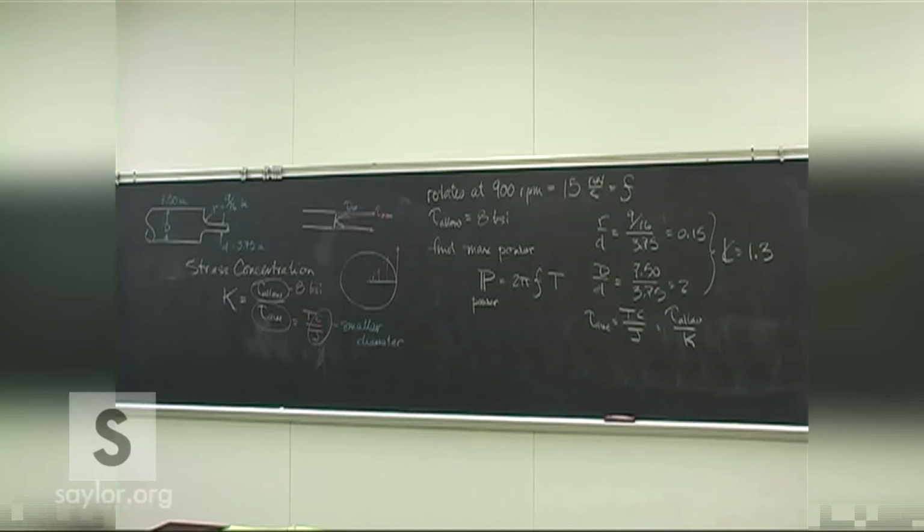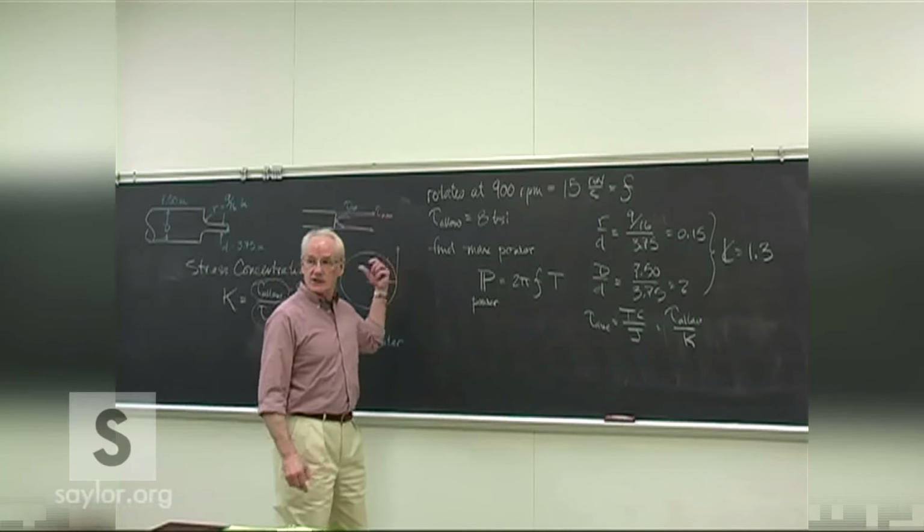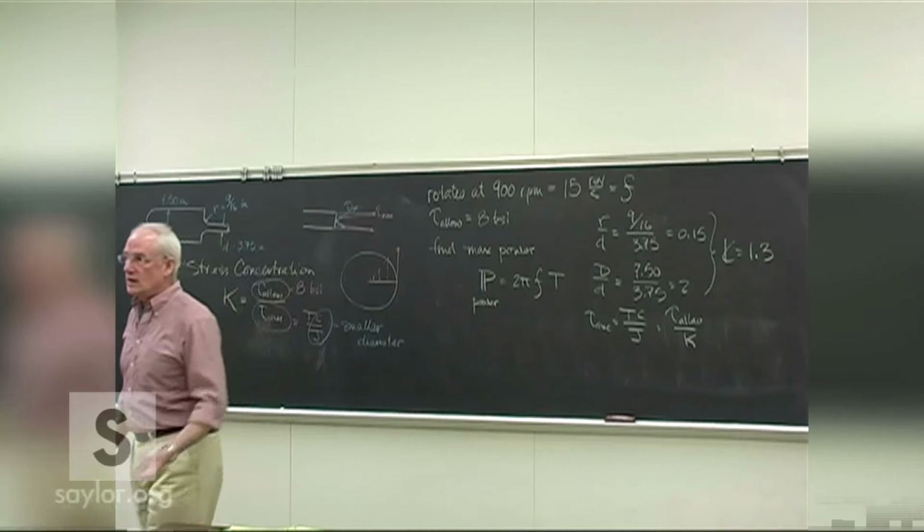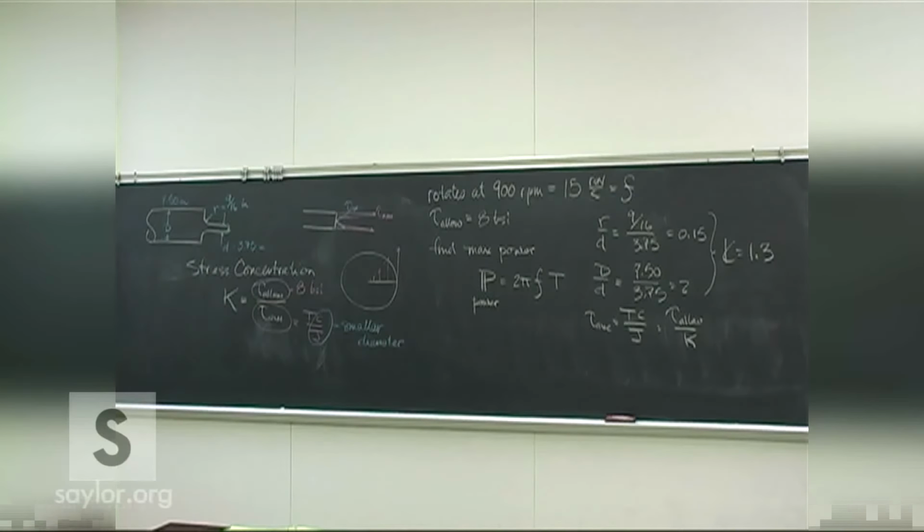Now, horsepower. No, you put it into horsepower, because when you go down to Ace Hardware and you're looking for a motor to connect to this shaft, he's gonna wanna know horsepower, because that's how they sell it down there. I mean, Earl's a bright guy, but he wants horsepower. 550 foot-pounds per horsepower.